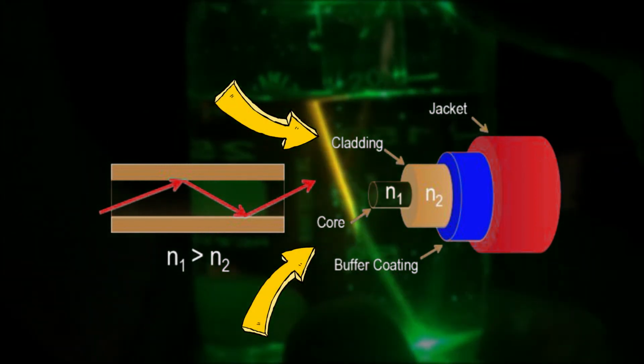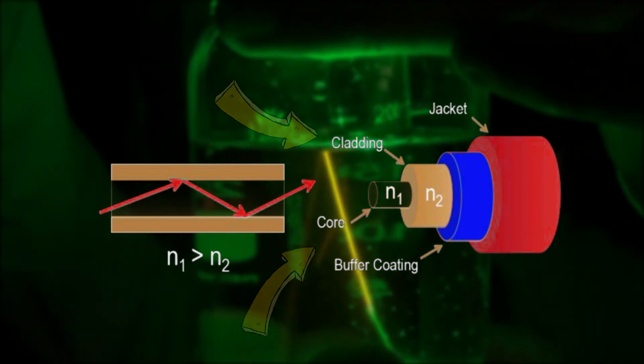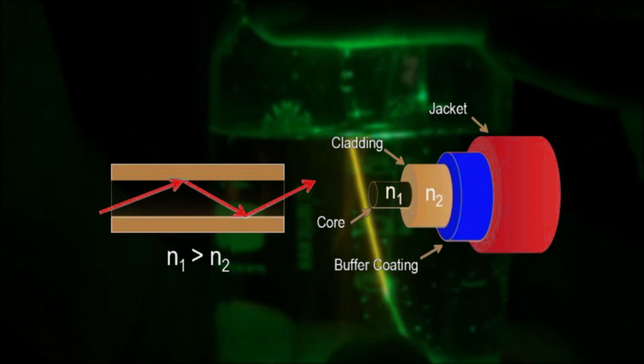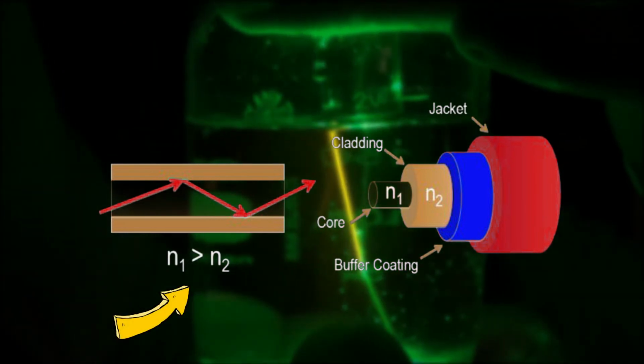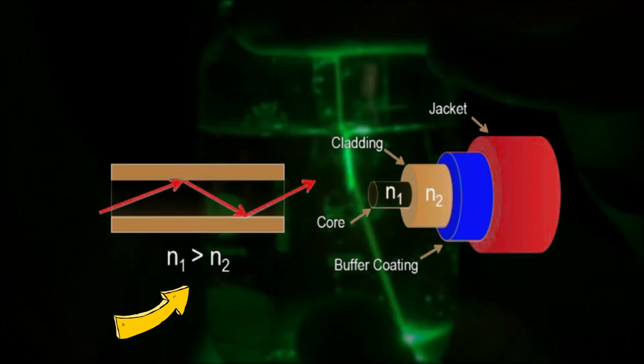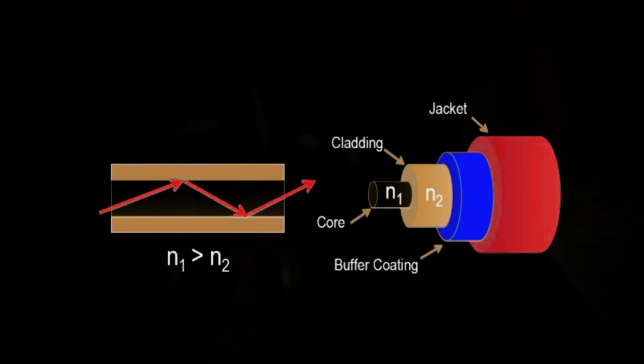and it is the working principle of optical fibers. The material where the incident light hits is the core, and it should have a higher refractive index than the other medium, the cladding. The changing of the cladding material will change the critical angle, which means that the higher the cladding refractive index, the higher the critical angle will be.